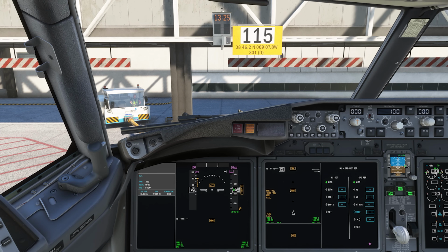Additional features which I hope to show in a different tutorial in flight are the autopilot roll saturation alerts and enhanced bank angle warning. So autopilot roll saturation: the autopilot on the 737 doesn't have any rudder input, it's only roll and pitch. If you basically saturate the autopilot by, say, an engine failure or rudder input, the aileron gets to a limit and it will advise you that you're reaching that limit and ask for you to apply rudder and essentially remove that saturation.